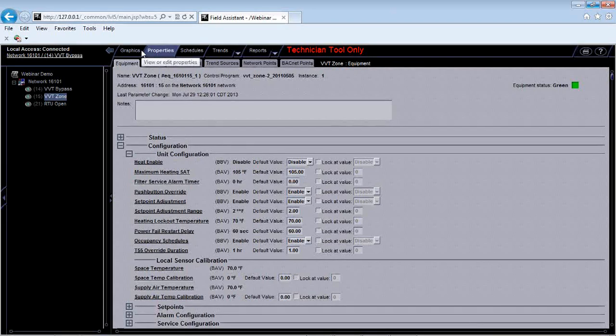So with this supplier sensor temperature, you want to put it somewhere between, depending on how much heat you're getting out of your rooftop. I usually set it at around 100 to 110, depending on how high heat readings I can get out of my rooftop unit. But if the supplier temperature goes above this value, you will go into alarm, and there will be an alarm displayed. So you need to base it on the type of system you have, how much heat you have on your rooftop unit. But ideally, you want to be putting out 90-degree discharge air for heating.